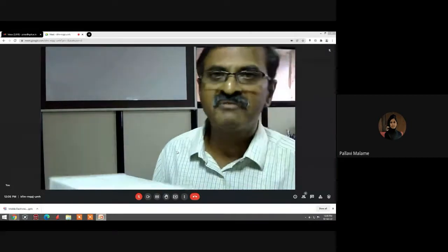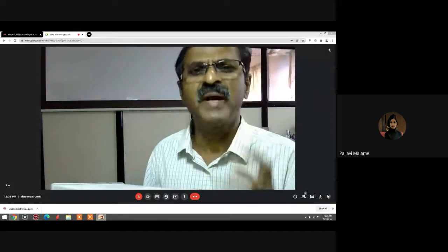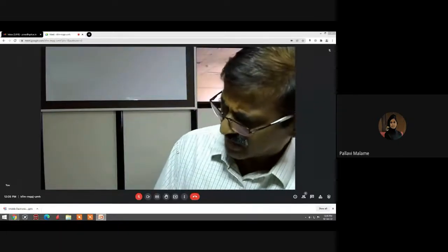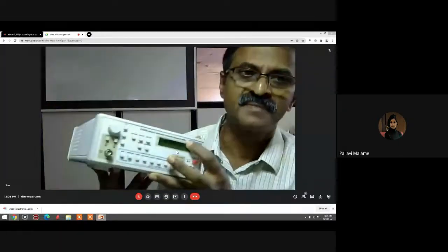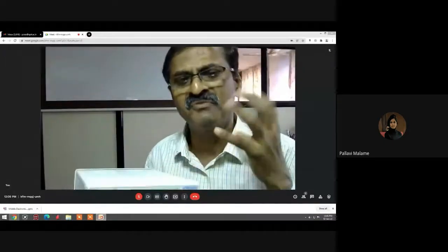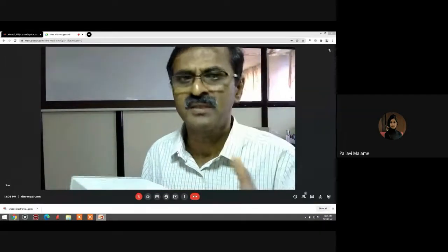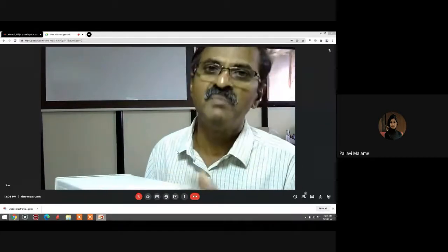Frequency range. What is the maximum frequency a function generator can generate? Say, for example, in this case, it says 3 megahertz. So 3 megahertz is the maximum frequency it can generate. So anywhere between 0 hertz to 3 megahertz, you would like to have a variable frequency.